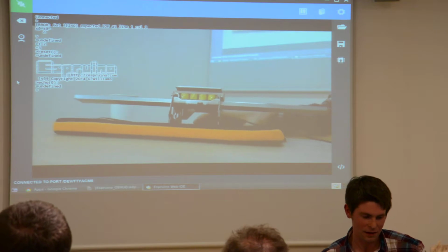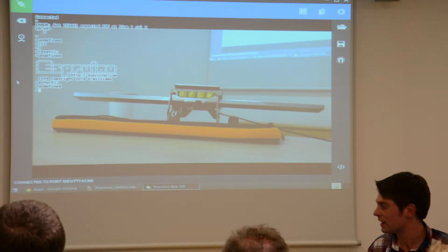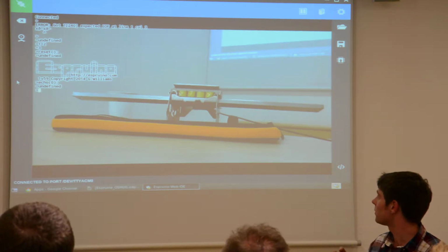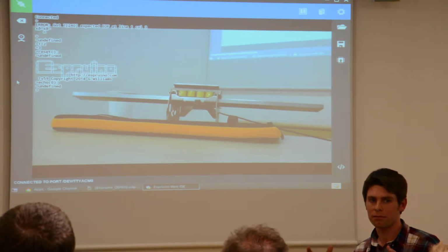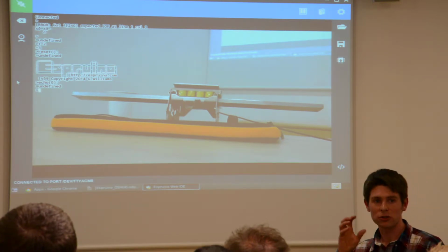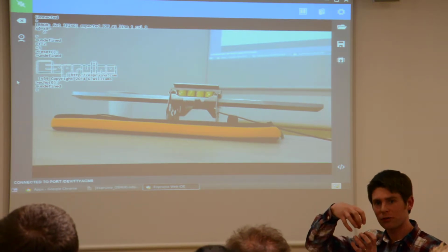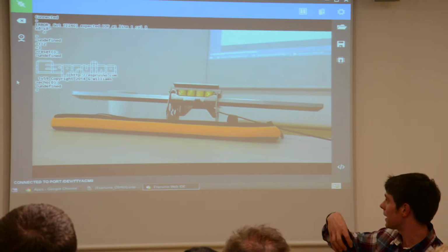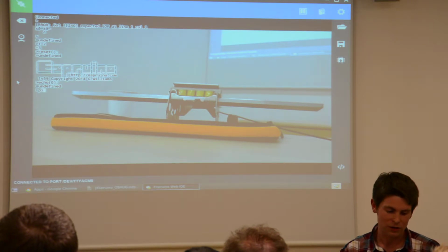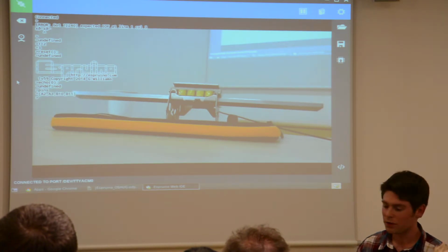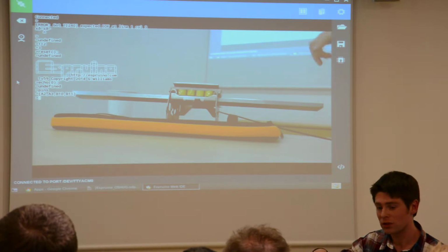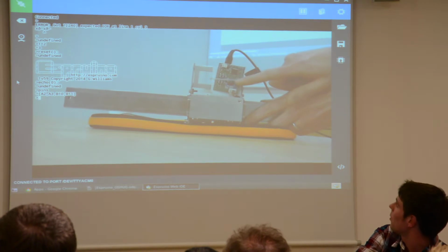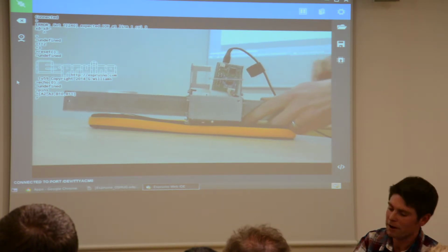So this weird-looking bit of stuff is a linear stepper motor out of the printer. I don't know if anyone knows a stepper motor, but it's like a brushless DC motor. You've got coils, and you energise one coil, and it pulls the motor round to face it. So if you energise all the coils in order, you'll be able to make it move. So on that array that I just sent over were the 4 pins that go to a motor driver, which is actually soldered on, see my finger, onto that little surface mount prototype area.